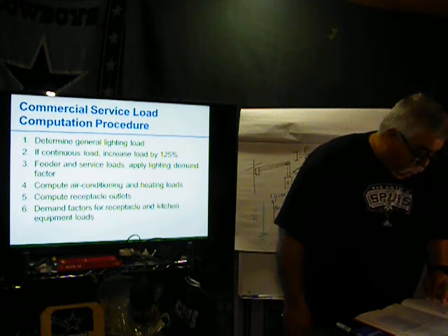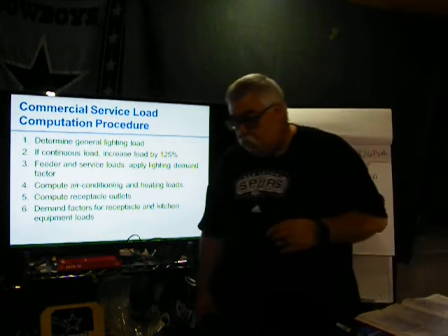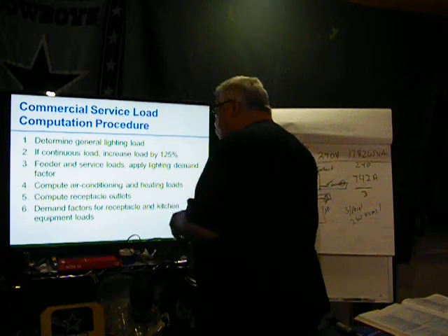Providing there is no discharge lighting on the neutral load. If over 200 amps, it can be derated by 70%, refer to section 220.61. Okay, so 220.61, you can derate your neutral.